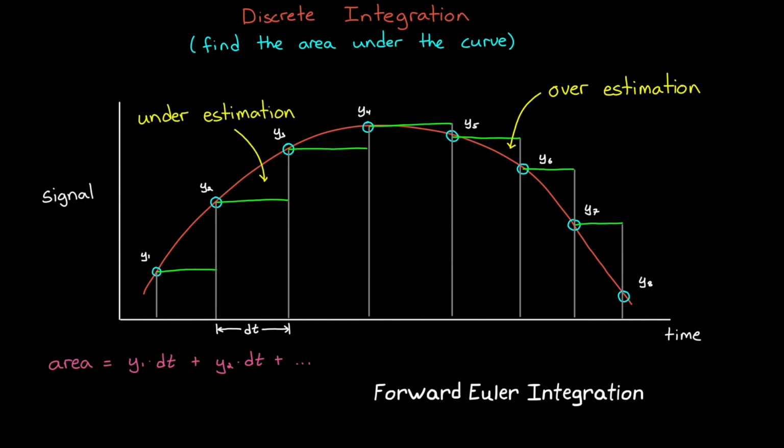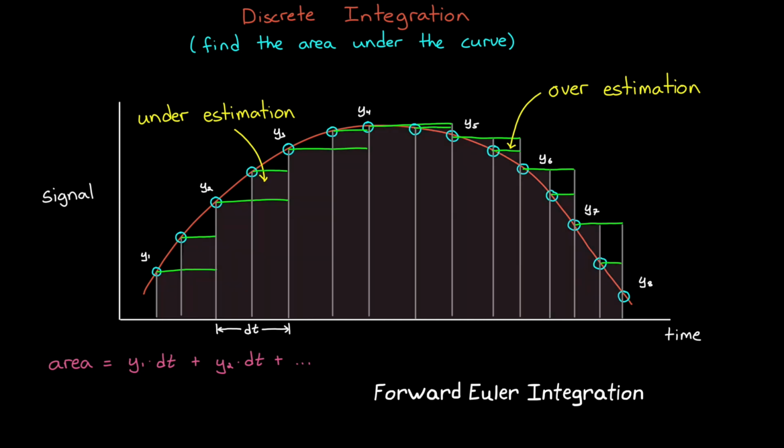We can decrease this error by lowering the sample time, which means that we're holding the value constant for a shorter time before the code runs again and updates the variables. But the lower the sample time, the less time we have to run the code since it has to finish running in this amount of time. So there's a limit to how short we can make it.